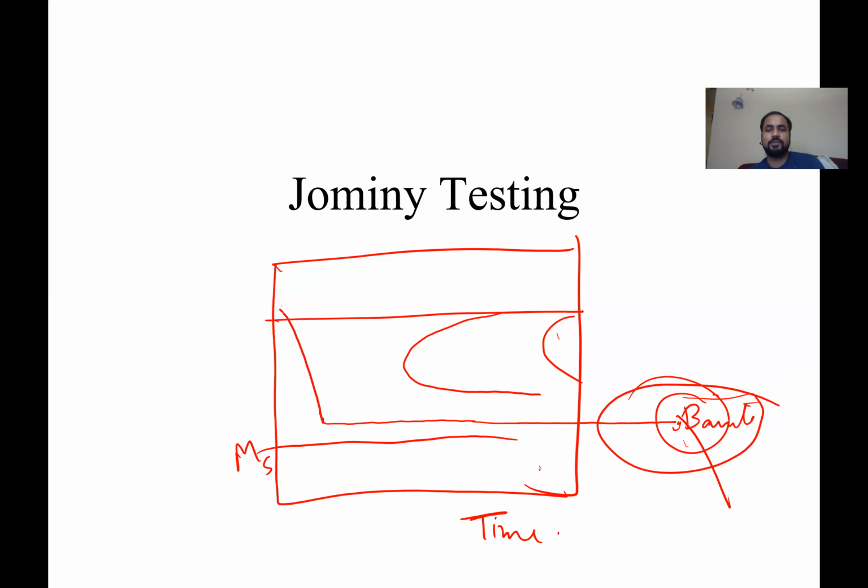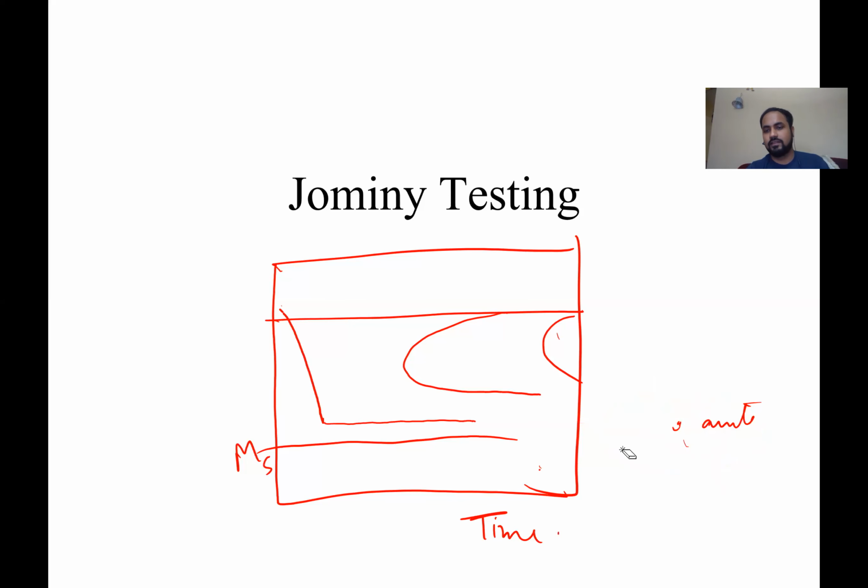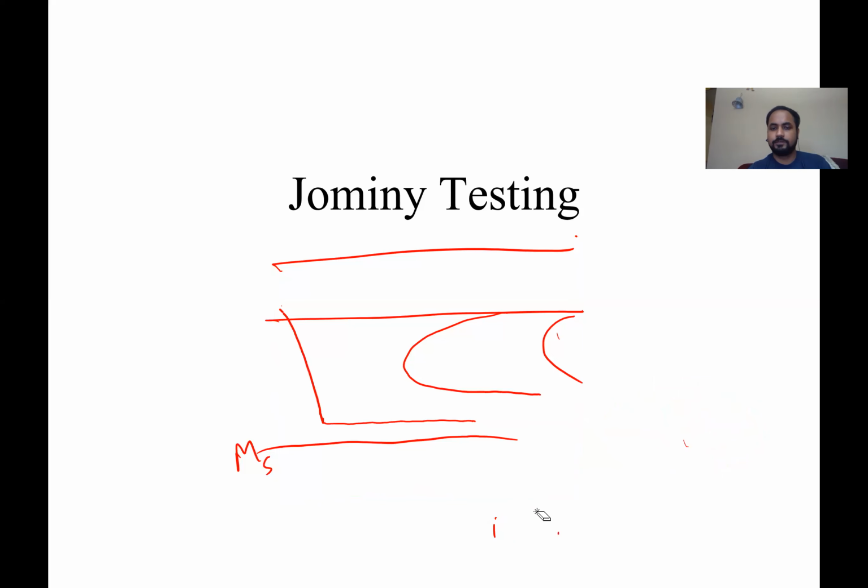So people didn't focus so much on bainite for practical industrial applications. From a research point of view, people are doing a lot of research on bainitic steels because there are certain specific properties that the bainite phase can provide. So now people have got really interested in studying bainitic steel, and they're trying different methods to make the formation of bainite easier.